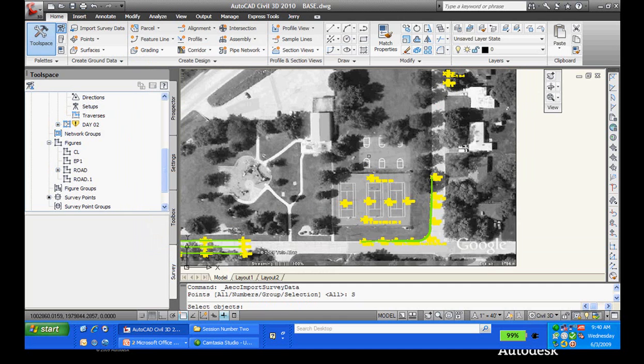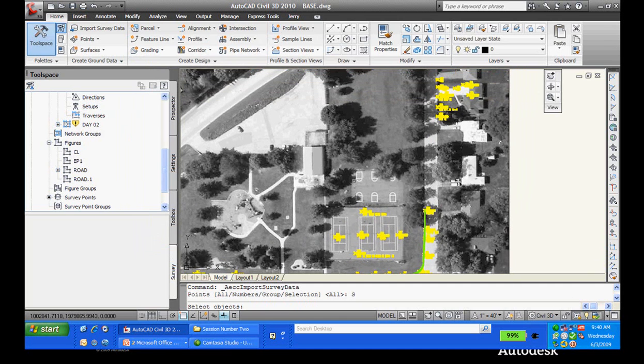We'll cover a cool command in AutoCAD, if you haven't seen it before: WP. W gives you a window. C gives you crossing, which picks up everything within the window when it touches. If you say WP, you get window polygon, so I can be like a surgeon here and pick out exactly what I'm looking for. I want to pick up just that stuff. If I had grabbed it with a window, I might have grabbed something I didn't need. Some real cool ones if you haven't seen them before.